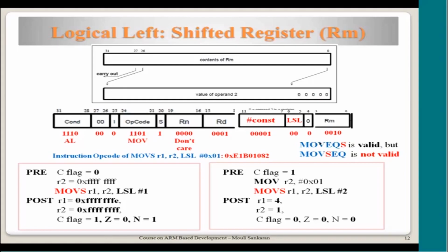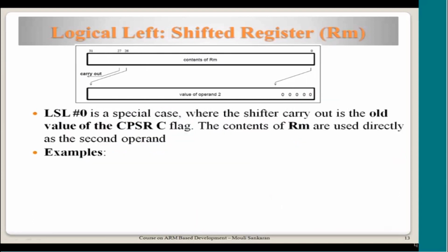So first the operation to be performed, and then if conditional things are there, EQ, NE or AL, whatever, give that, and then the S flag if it is required. So this is all optional. If you want to mention the condition and whether you want to impact the condition flags, you have to mention this S. Okay.